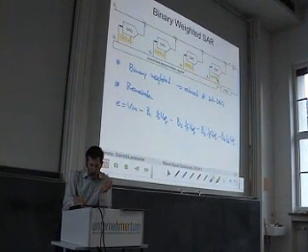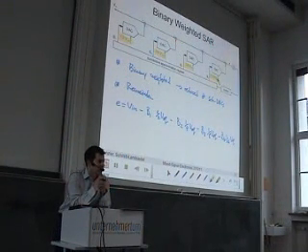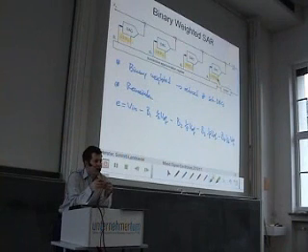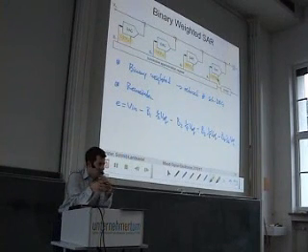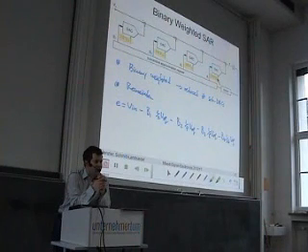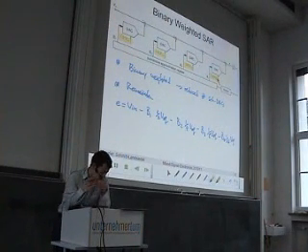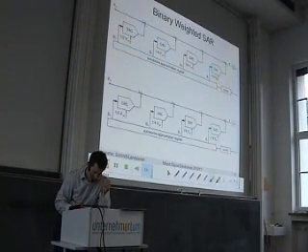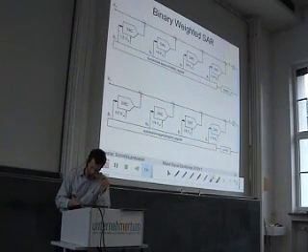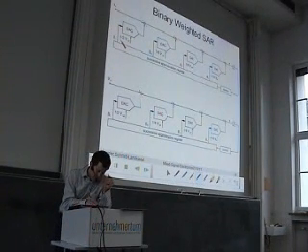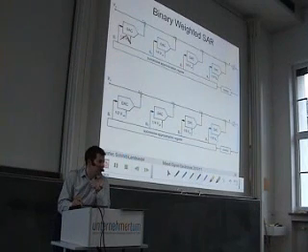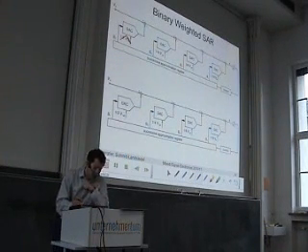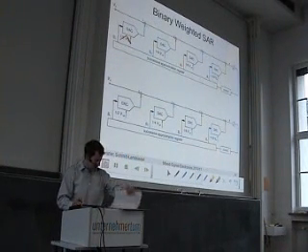We have 4 different reference voltages. So basically you have to build 4 different DACs here. So the question is, can we simplify this somehow? And what we could do is to say, well, we remove the scaled reference voltage and we put a scaling factor here.